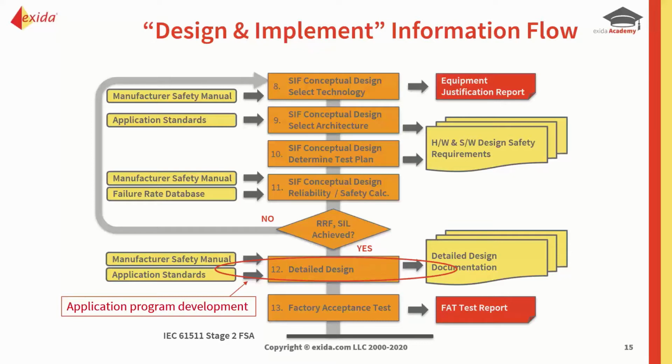And you'll notice, and those of you that have been on my courses know, I like to throw in the term RTFM, read the flaming manual. So you really need to have the safety manuals for the equipment that you've chosen, because the safety manual is very important. It will contain certain information that's relevant to the specific SIL that we're trying to meet.